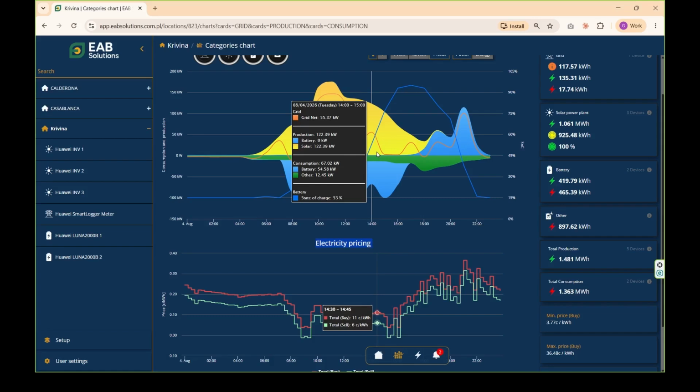In that case, if our EMS failed, the battery failed, and the internet failed, there'd be no problem. The PV inverters would keep producing energy that the client would keep consuming, and if the client doesn't consume it before it goes to the grid, the data logger would prevent it by sending a power limitation set point to the PV inverters.